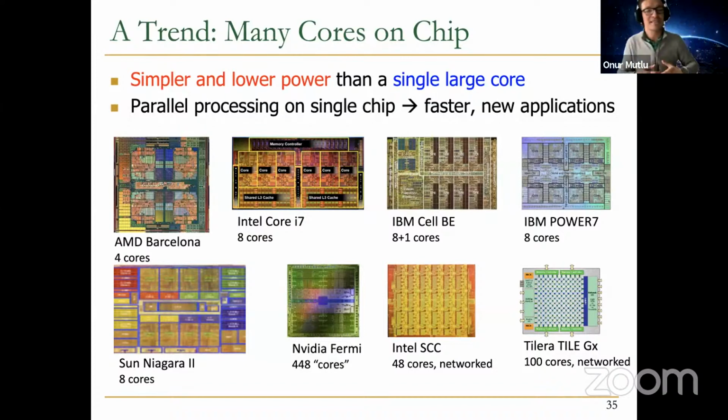And people tried to scale the performance of that single core, and they said this is too hard. There are a lot of good ideas to scale the performance, but the energy and complexity increases significantly. So at some point, the industry decided to, instead of increasing the core performance a lot or dedicating all of the transistors in a single chip to a single core, dedicate these transistors to multiple of these processing cores. Now they're building multiple cores, basically, many cores, let's say.